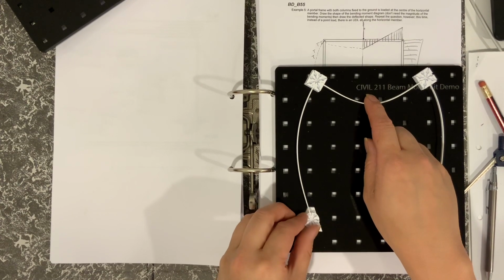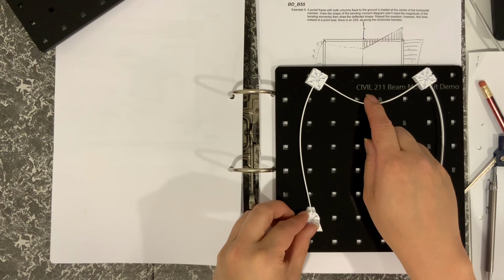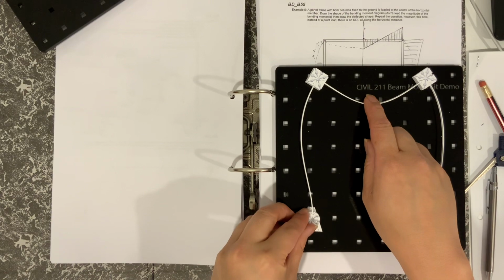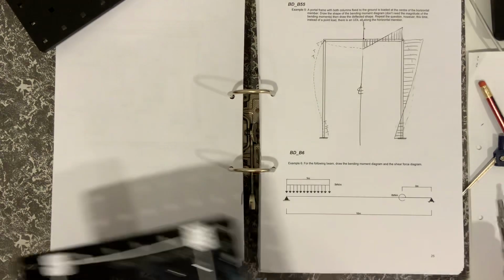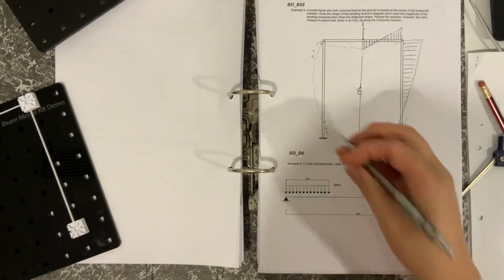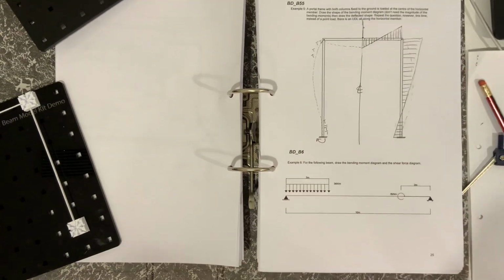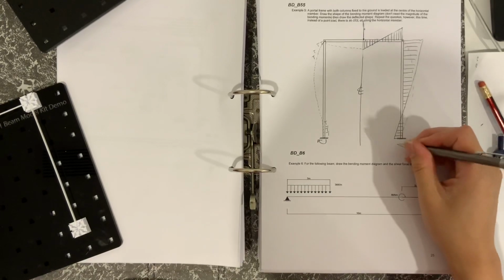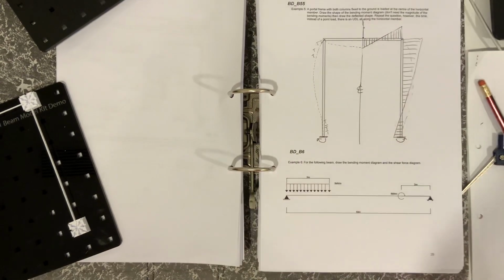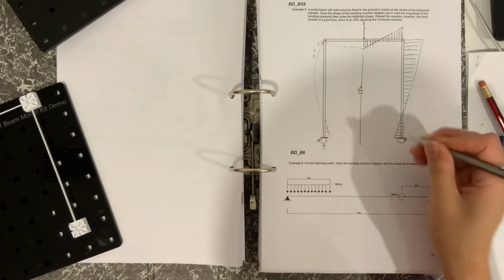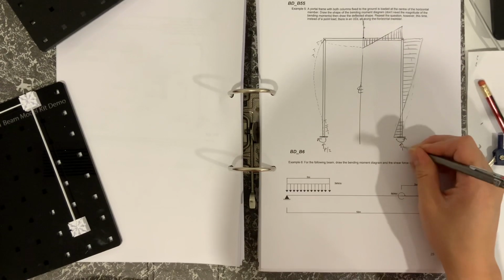And I'm having to apply a moment in the clockwise direction. So my moment is clockwise to get that back to 90 degrees, so the reaction there is in that direction, and by symmetry the reaction on this side here would be in that direction. Okay, and then the vertical, or the axial one, would be P over 2, and then P over 2.